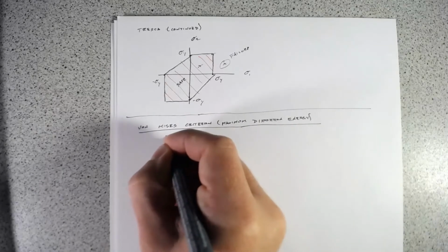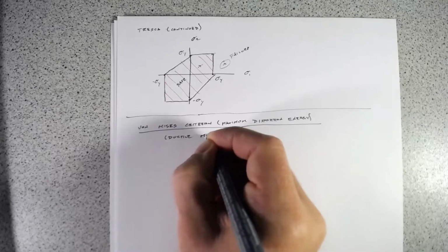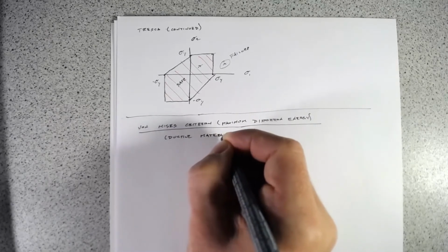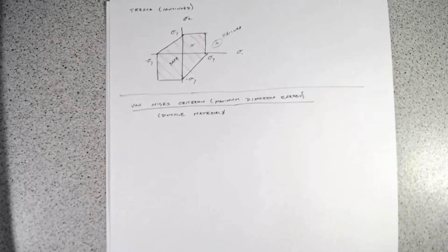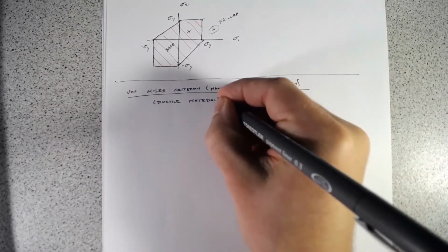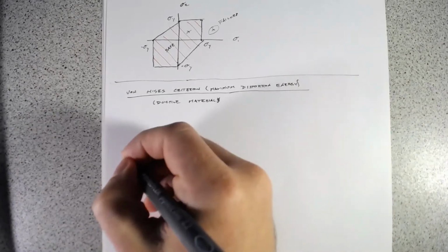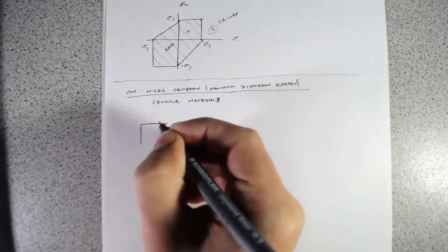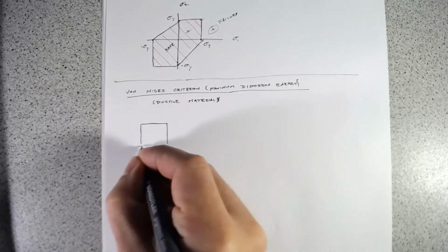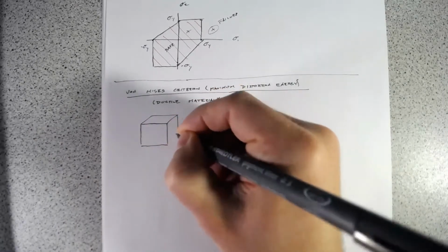And again, this is for ductile materials. And so while the first two criteria are really quite straightforward to derive, this one's a bit trickier, because what it's saying is that it's relating really the change in volume and what the strain energy is for that respective change in volume.